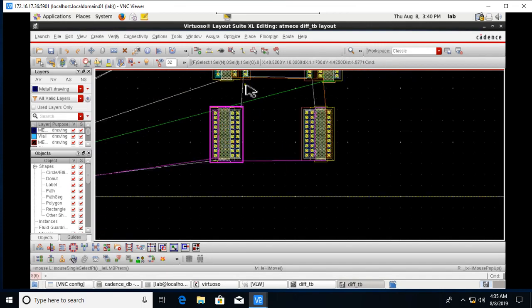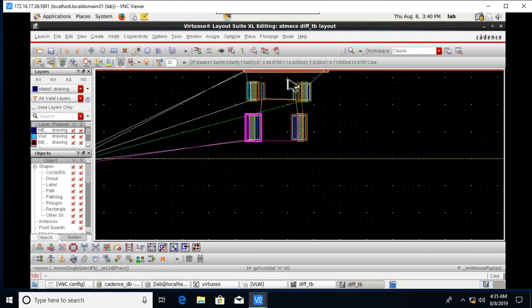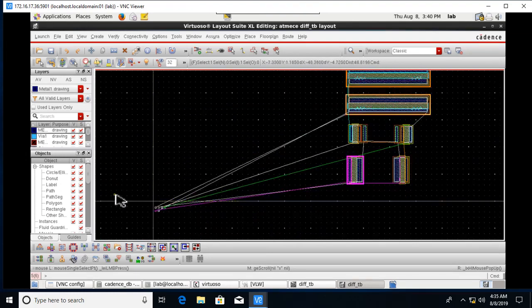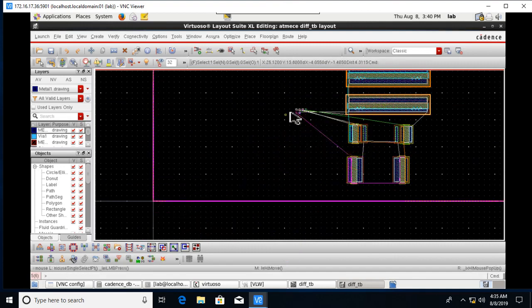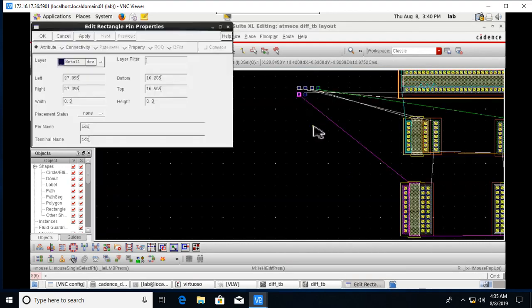After proper placement of the components, now we'll go for the pins. Move to any one corner as per your comfort, and click on each pin to know which pin it is. Just click on it and press Q or go to properties.